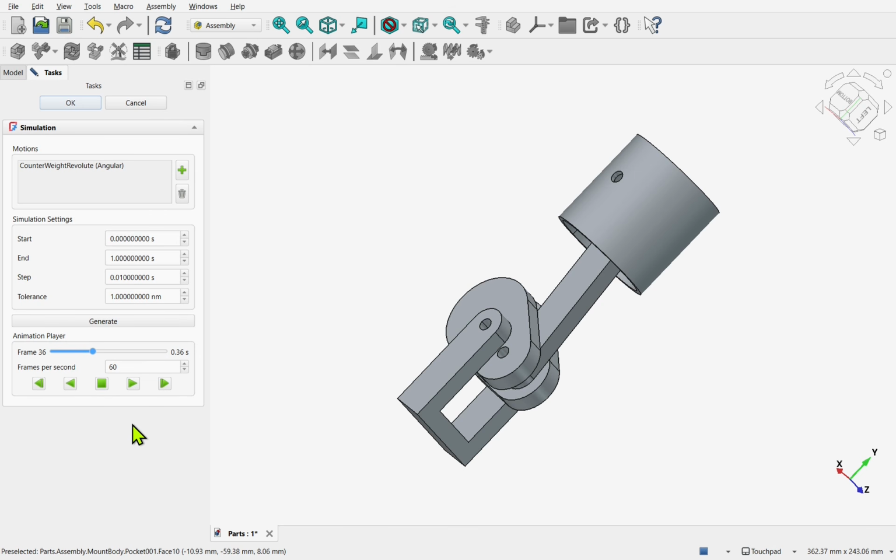You may experience that your animation breaks and you'll find one of your parts that's connected with a joint is misaligned or somewhere off in space. If that happens, cancel the simulation and then reapply it. Final note is that the smoothness of the animation depends on your CPU performance and how complex the assembly is. The more linked joints involved in the simulation, the higher the load on the CPU. You may need to fine-tune these settings, balance the performance and smoothness of the animation. Hope you enjoyed that lesson, and I hope to see you in the next one.